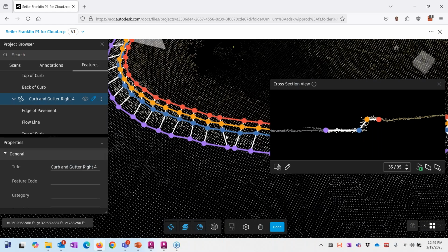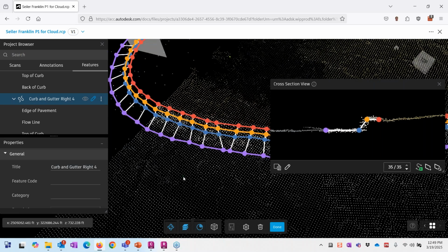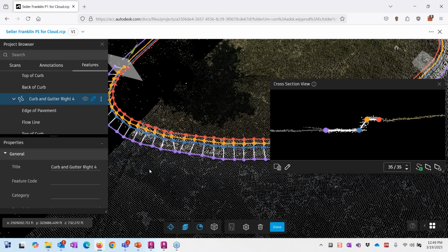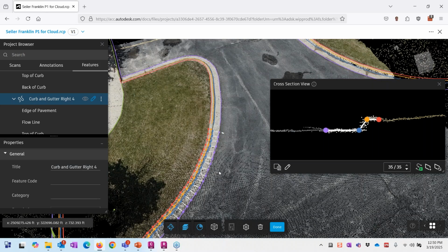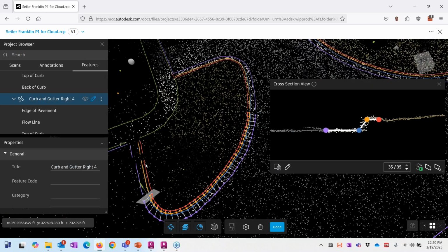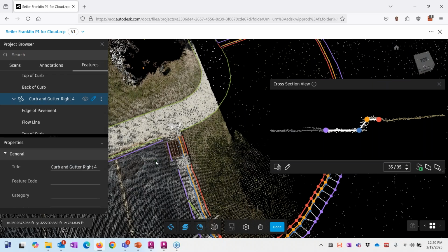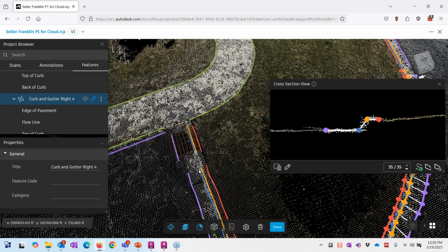So I didn't have a cleaner point cloud at the time when I was running this, changing computers around. So with what I've got, I really probably could have gotten better with a denser LiDAR on that. But you might not get 100%. But in areas where it's going to be kind of nebulous, you're going to have to go through, probably go back and collect some data manually or refly that portion of it.